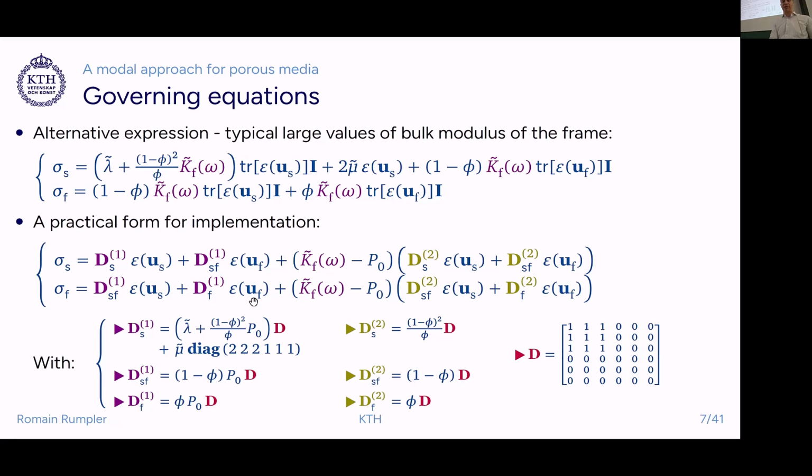You see here there are two parts of the emerging stiffness matrix for the finite element problem, the low frequency limit there and the higher frequency limit there. What you can see is that it depends on those submatrices, and they are all dependent on the same submatrix D, which is only made of the longitudinal directions and the coupling between these compression extension terms. That indicates there is some kind of regularity in the structure of those matrices, which maybe makes for a suitable enough eigenvalue problem where the modes could be helpful for the global problem that we have in the end.